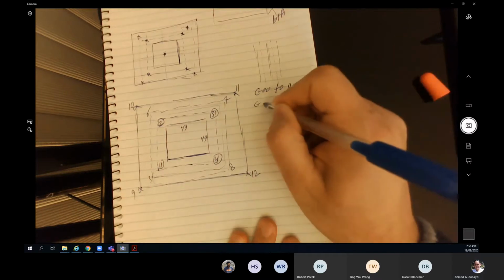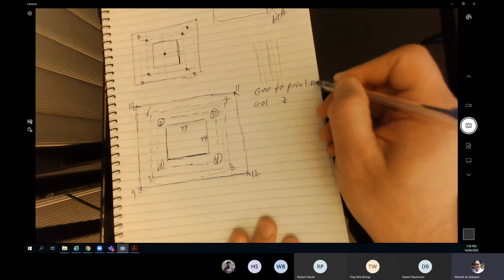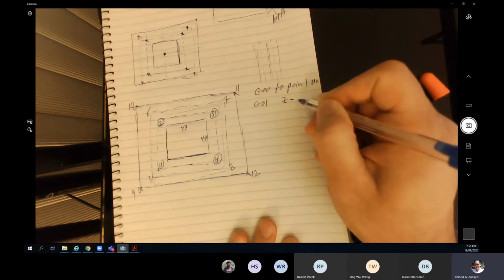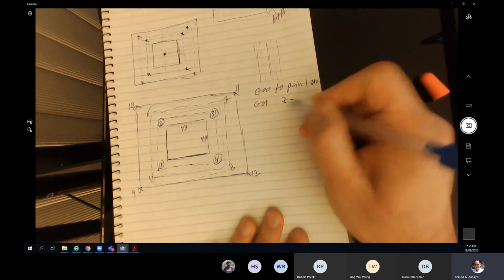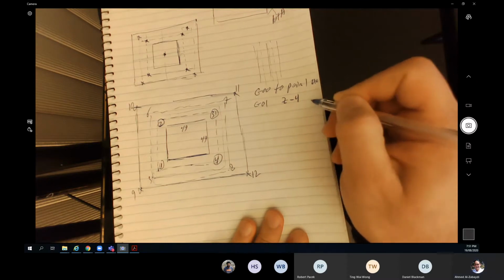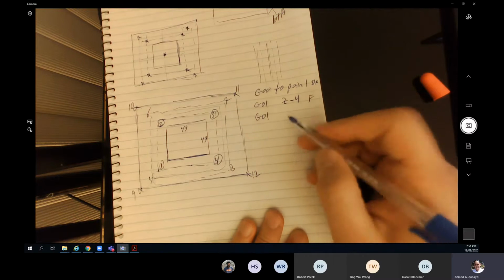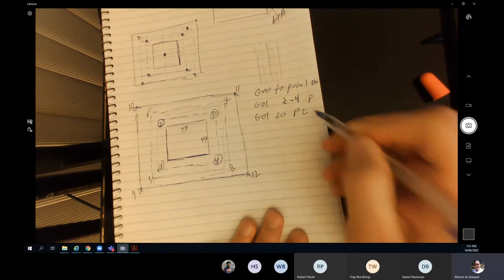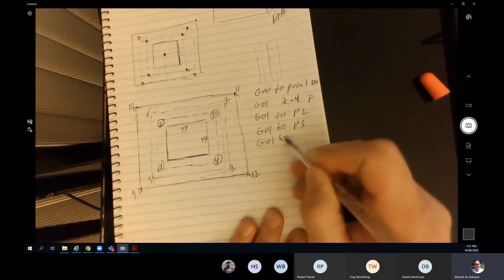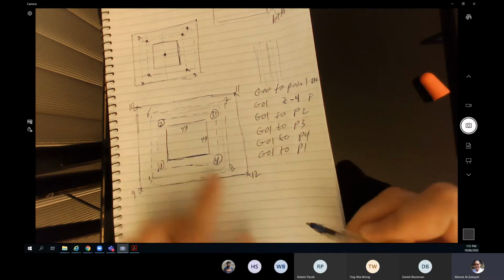And then G01 to the Z equal to, of course, the Z here was 10 at the beginning. Okay, to the Z equal to minus 6, if you want to do it in one shot, or you can do it in multiple stages. So the first depth is going to be equal to minus 4 millimeter, for example. Then you write down the code G01. You have to add the feed rate, by the way. Okay, G01 to point 2, G01 to point 3, G01 to point 4, G01 to point 1. We need to go back.